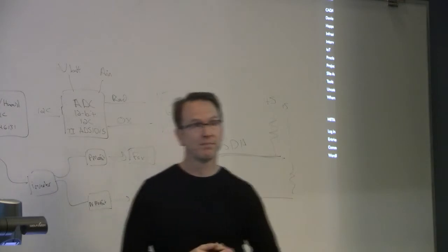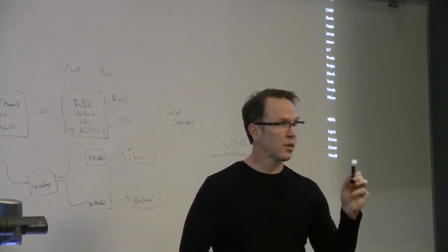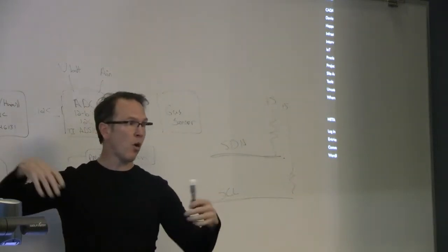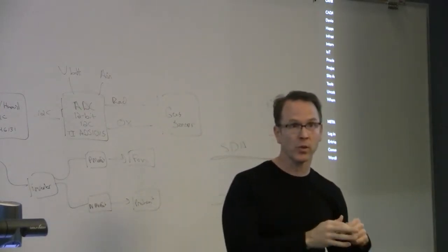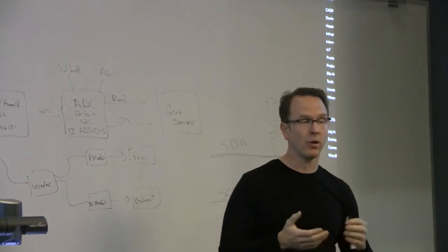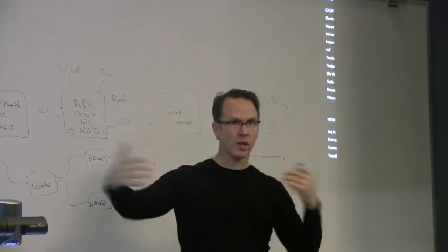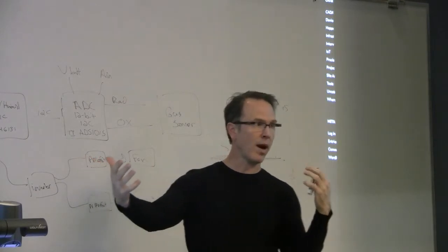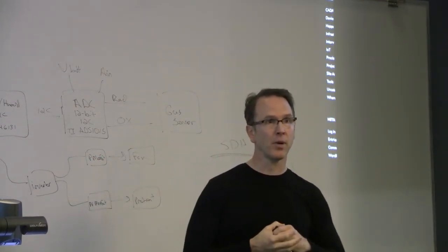It does all the pins that need to be shifted, 4 channels. It's specifically for I2C, but it will also do all the higher bit rates of I2C. The other thing you may not know about I2C is you can run at different speeds, and that's when you get into how big your pull-up resistor is, what's the capacitance of the wire, how long is the wire, and all that kind of craziness. And this thing can operate at those higher speeds.